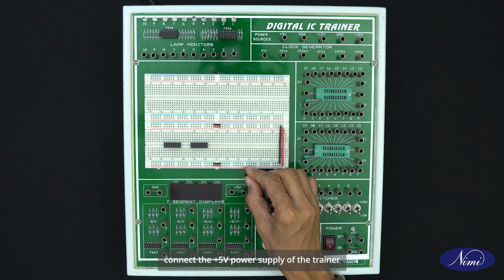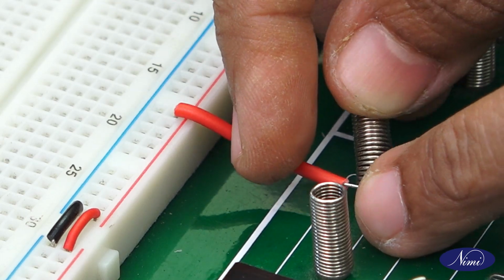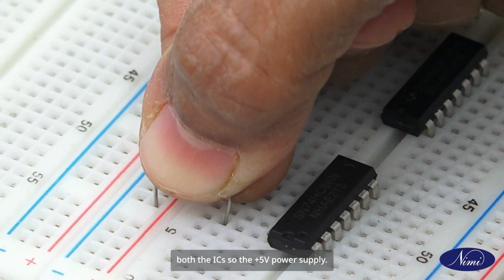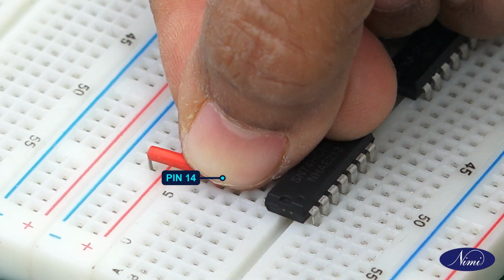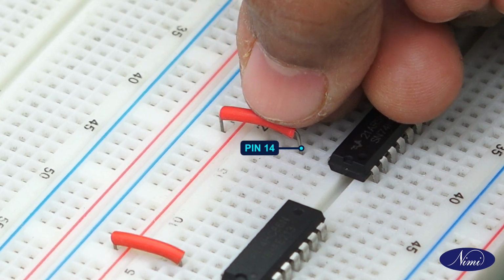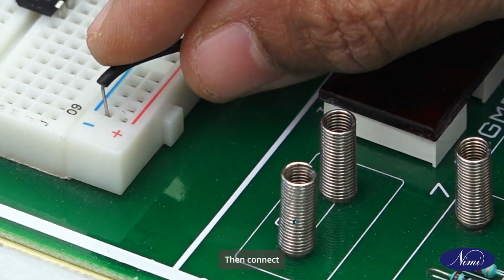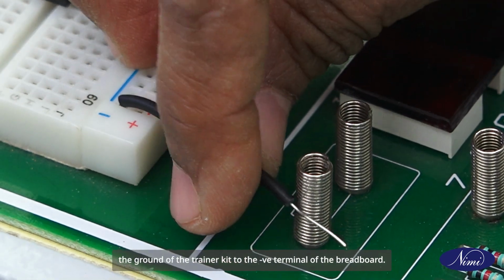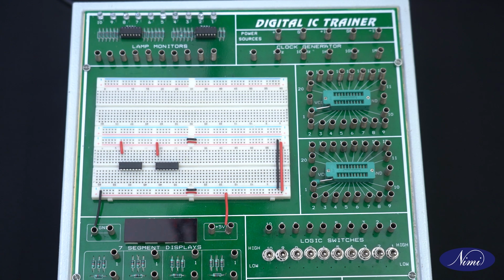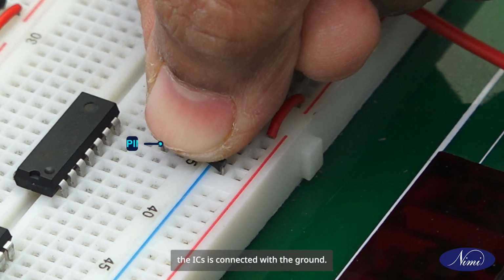Connect the plus 5 volt power supply of the trainer kit to the positive terminal of the breadboard. Next, connect the 14th pin of both the ICs to the plus 5 volt power supply. Then, connect the ground of the trainer kit to the negative terminal of the breadboard. Next, make sure pin number 7 of both the ICs is connected with the ground.